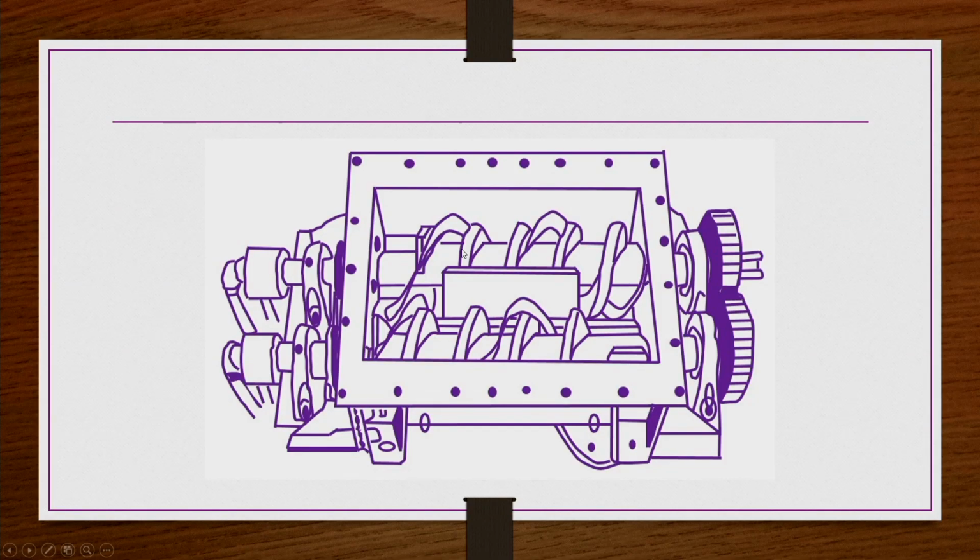Now we see a schematic of a typical low speed horizontal mixer granulator. So here we have a shaft, and there are actually two rotors, 1 and 2 like this. Onto this shaft we have blades, which are provided something like this. This is actually a double trough design shown here. So these blades are like this.